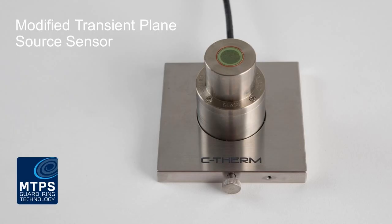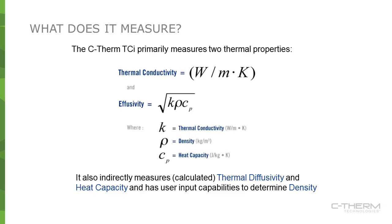So I want to describe a little bit the principles of operation to the MTPS method, just so we have a baseline understanding of how the method works. First off, it's important to understand what are we measuring. So the MTPS sensors measure two thermal properties. The first is thermal conductivity. And most folks know what thermal conductivity is, a fundamental heat transfer property. This can also be expressed as R value if you consider the thickness for the sample, but it's an indication of the quality of the insulation of the material or the heat conduction of the material.